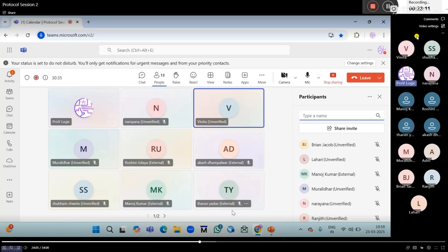If you see I2C, SPI, APB, AHB, the write operation and read operation are not enabled at the same time. If write is enabled, read is disabled; if read is enabled, write is disabled. So bidirectional transmission can happen, but not simultaneously. But in AXI, USB and UART, both can be done in parallel, simultaneously.